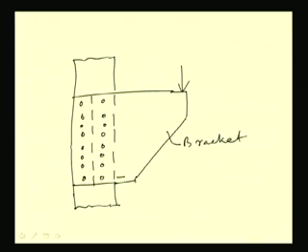So, this is an edge distance, let us consider say 40, and these are 50, and this is 120, then 60 into 60, and say this is taken as 40. So, we are assuming edge distance as 40.